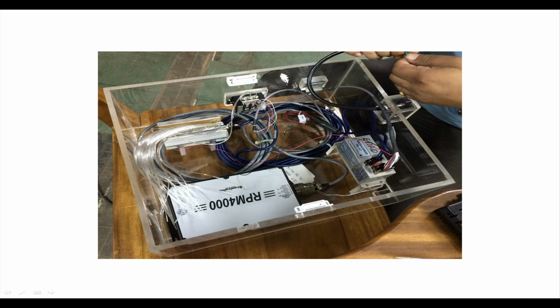You have accompanying hardware here, so it has to be interfaced with all that. Additionally, you have to produce some pressure of the order of, say, 60-65 psi and provide it to this pressure scanner. There are some specific ports available on the scanner so that you can operate it in a desired mode. There are different modes of operation of this scanner. In a certain mode you may be calibrating it, in a certain other mode you may be operating it for acquiring data and things like that.